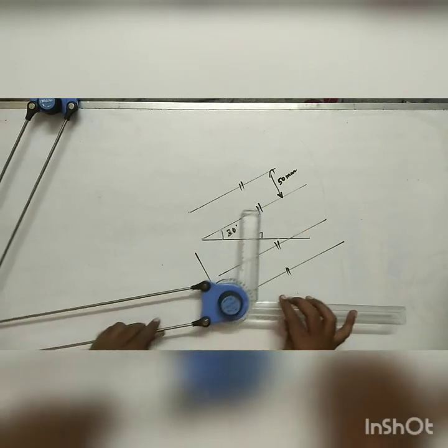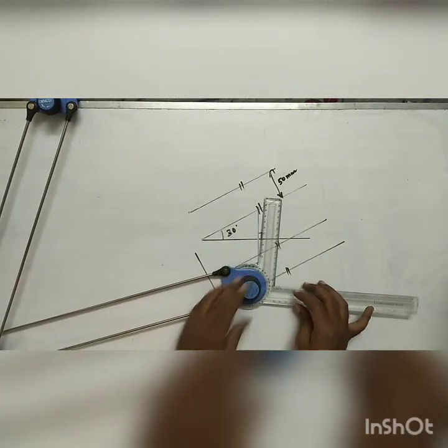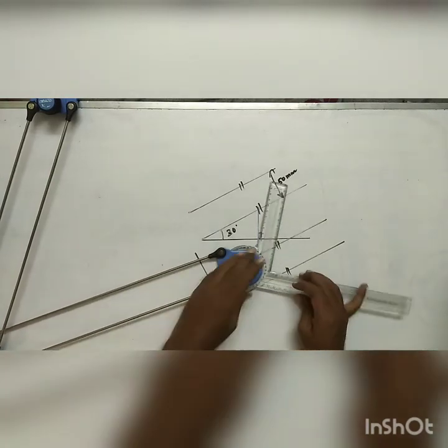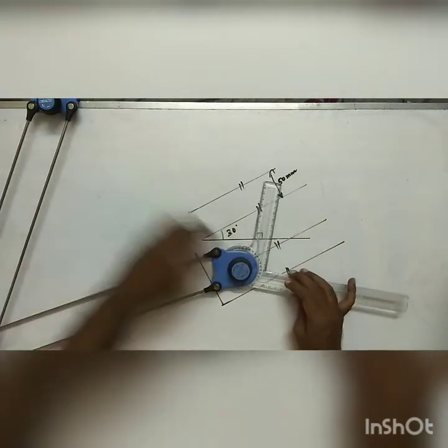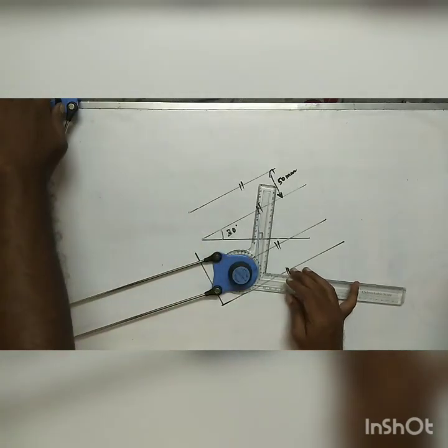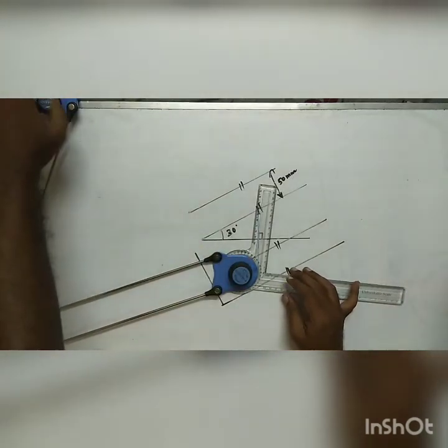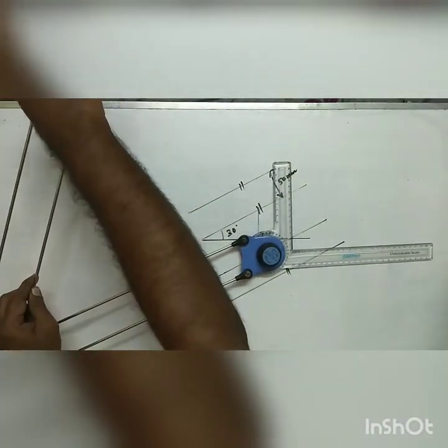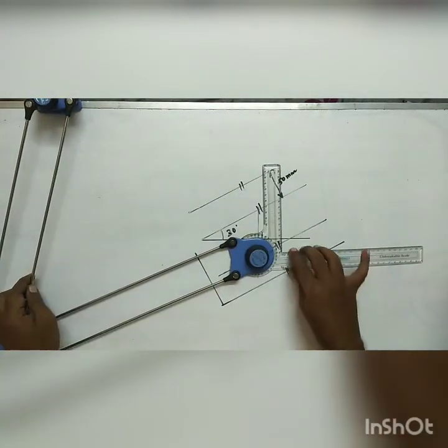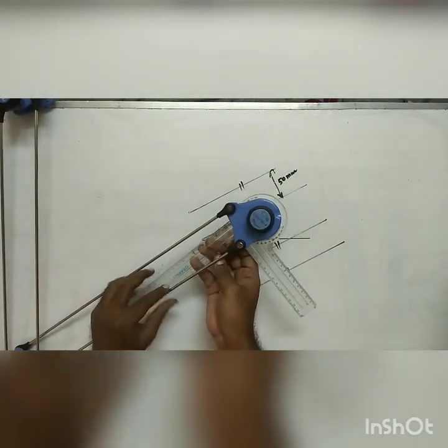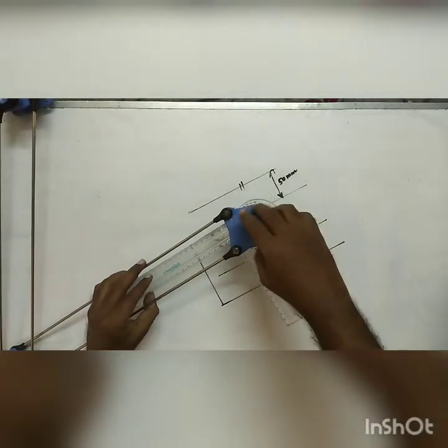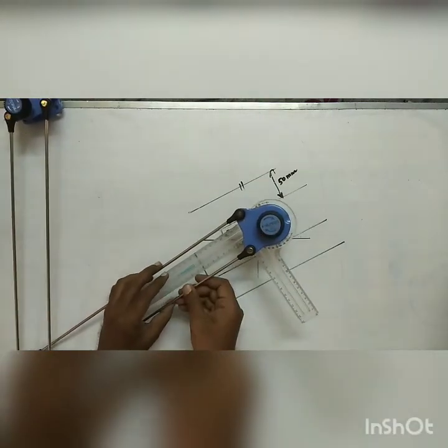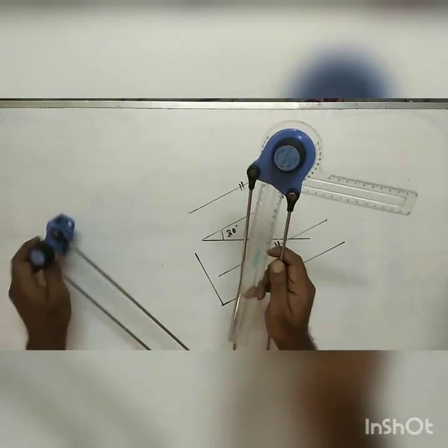And once you are done using the drafter, then try to remove it from your drawing board. That's also very important. We have to do it very gently. First, loosen this knob a little bit, and similarly loosen the clamp screw at the smaller side of the knob. Then you take it out, loosen this little to the full extent, then loosen this one. You already loosened it, right? Just keep it in this position and then tighten your knob. So do it gently, don't use a rough manner, that's very important.